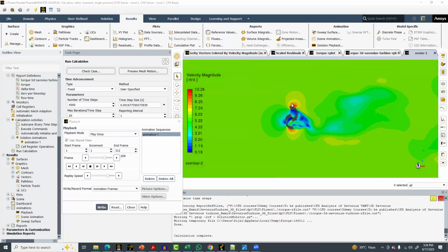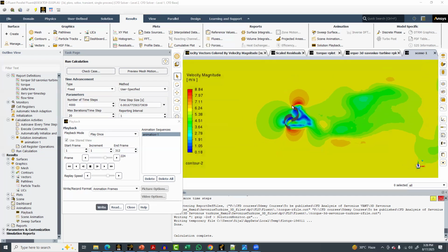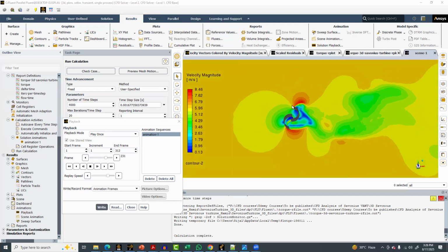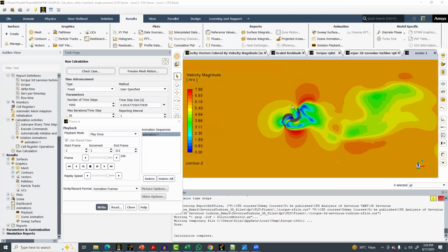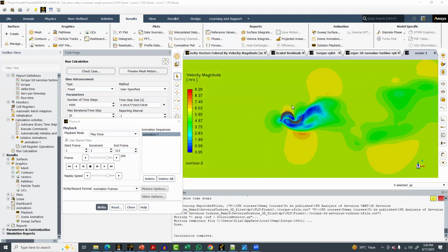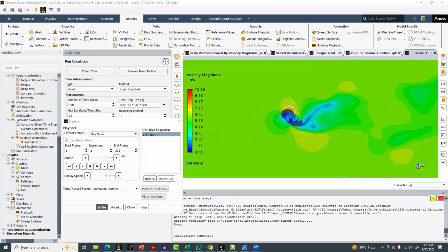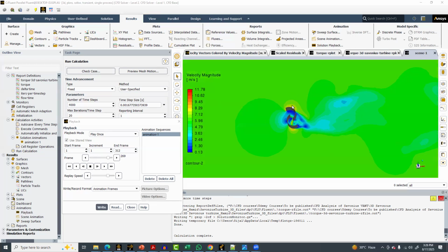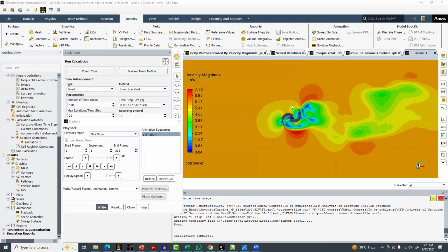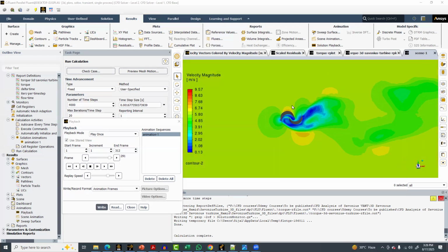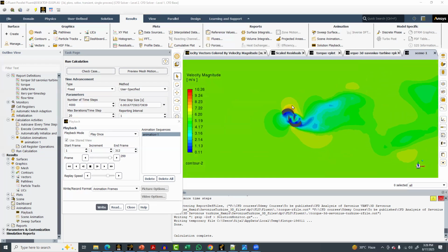Number two is that we use dynamic meshing when we are simulating starting torque values. Like a wind turbine starting: when the turbine is stationary and you want to see the starting behavior, driven directly by the wind forces. At that time, the sliding mesh cannot work because the starting RPM is varying, and it depends on the incoming wind speed.